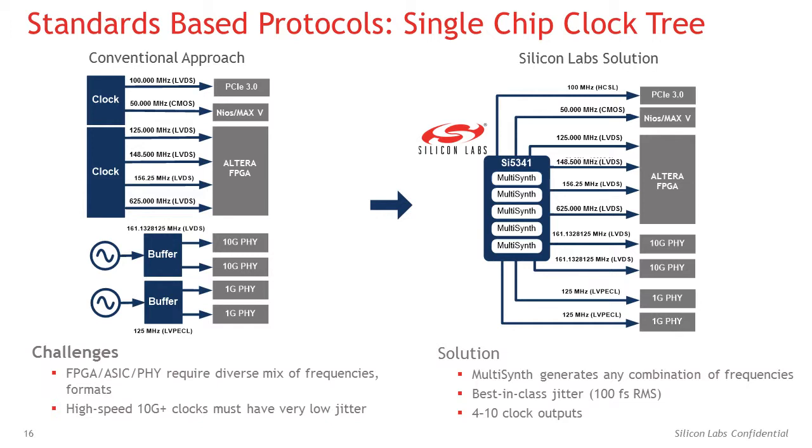And so what happens in order to hit all those different frequencies for all those different standards, hit the phase noise requirements for all of those specifications, and to drive things like the PHYs, if those phase noise requirements are very, very stringent, making it very difficult to hit all of those frequencies and specifications required across that board with all those chip suppliers, and not have it blow up into a very large, what we call a clock tree, where you have to use multiple dedicated local oscillators that can be very expensive, fan-out buffers, and other clocks, which will synthesize a lot of different frequencies for you.